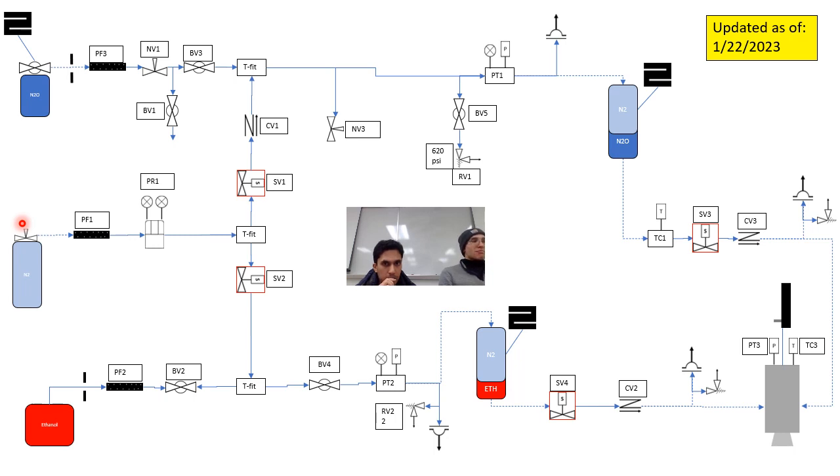So what's happening then, I think we might have already begun this process, which was depressurizing down to 625. We want to make sure that pressure transducer 1, PT1, is between 600 and 615, for example. Those numbers are subject to change as the logic changes just a little bit. It'll still be very much within that range between 580 and 620.